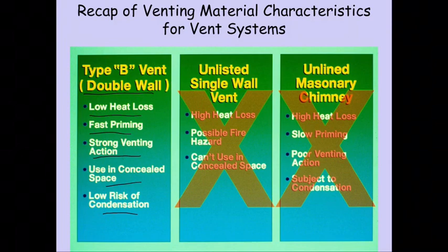And then, of course, a masonry chimney. For any new appliances or newer, more efficient appliances, an unlined masonry chimney is a problem. Even on older systems, I've seen systems put in an older home that did not have a masonry or a metal liner, and those chimneys were starting to degrade and fall apart.